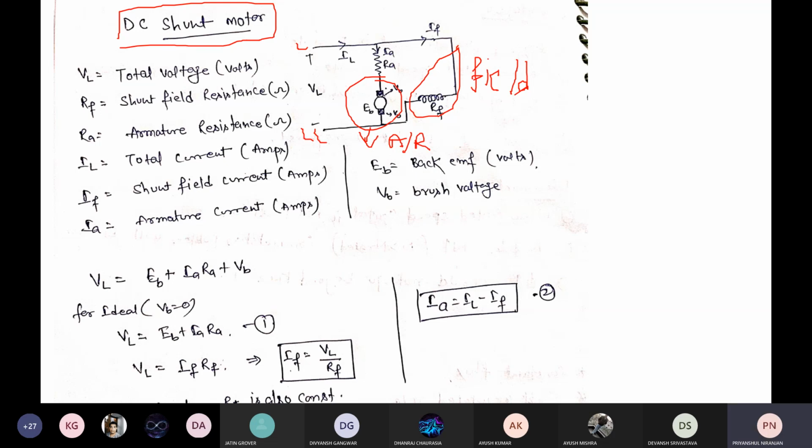When we design a DC machine, or an AC machine, there are two parts, the stator and the rotor. The stator is the stationary part where we place a winding, and the rotor is the rotating part where we also place a winding. So in the DC machine, the field winding is placed on the stator, because I am using the field winding as a constant.